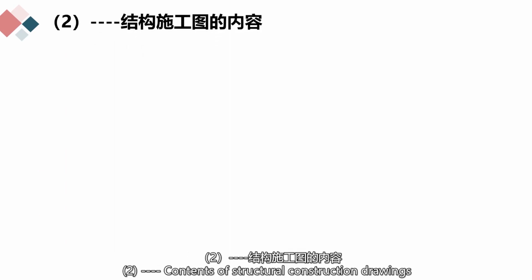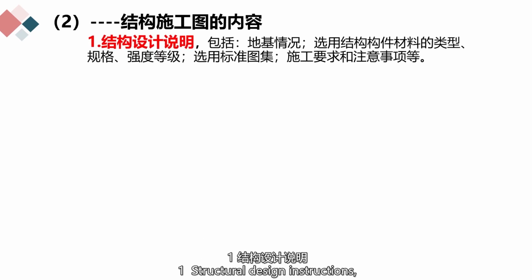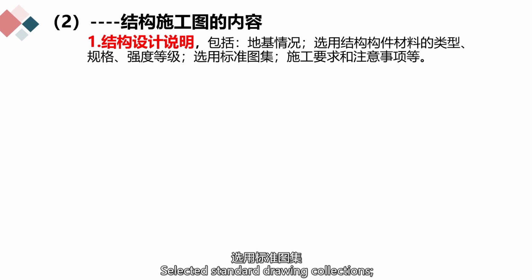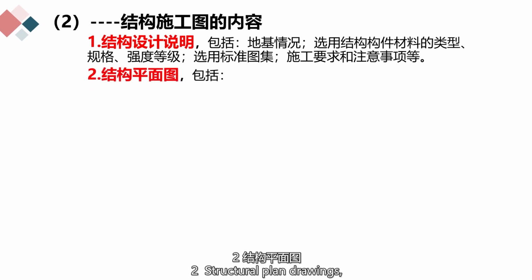2. Contents of structural construction drawings. 1. Structural design instructions, including soil conditions of the foundation, types, specifications, and strength grades of the materials for selected structural components, selected standard drawing collections, construction requirements, and precautions, etc. 2. Structural plan drawings, including: